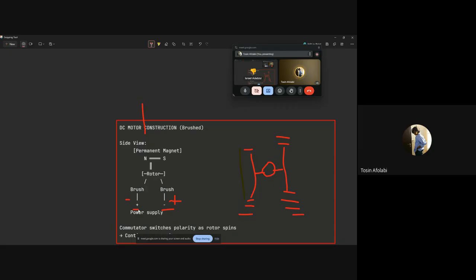So now the H bridge uses 4 switches. And the switches in our case are going to be transistors to control current flow between both directions. Now, because the Arduino pins cannot provide enough current, motors need about 0.5 to 2 amps to function correctly.